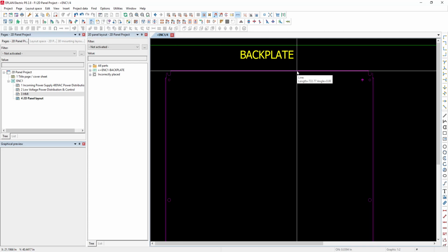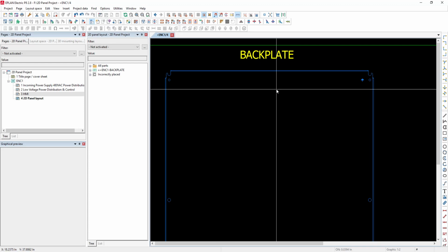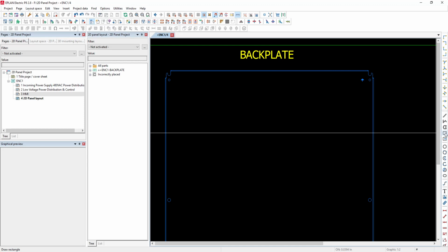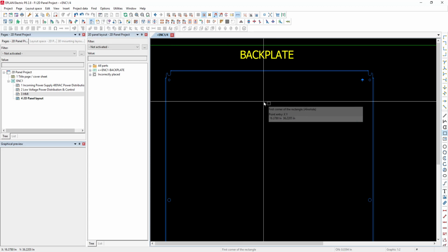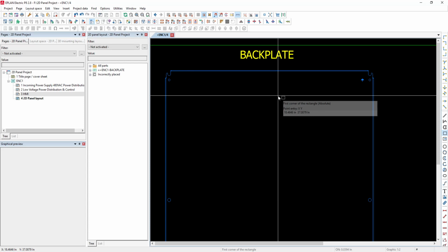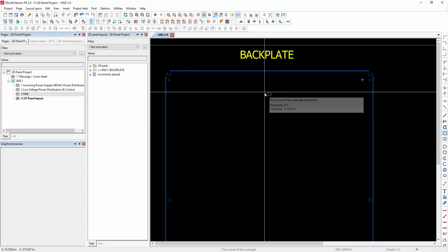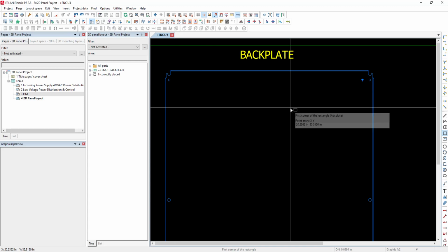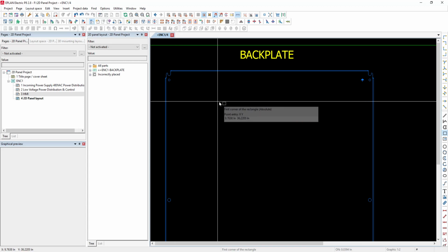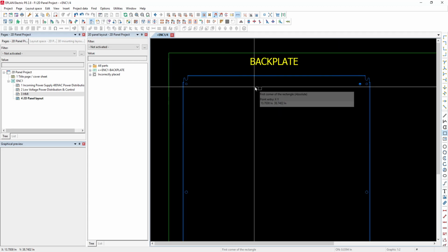So, to start placing a DIN rail. One of the disclaimers with DIN rails and wire ducts is that in the panel 2D, as opposed to the Pro panel, this has to be a rectangle. So it's either a rectangle or a line. There's no real smarts to it, unfortunately. It wasn't conceived that way. It's very basic, just to put objects and assign positioning, dimensioning, and so on, so guys on the shop floor can have a base understanding of where to do this. Just like any other drafting tool where you can draw polylines and squares and text and rectangles, it's kind of the same base principle.